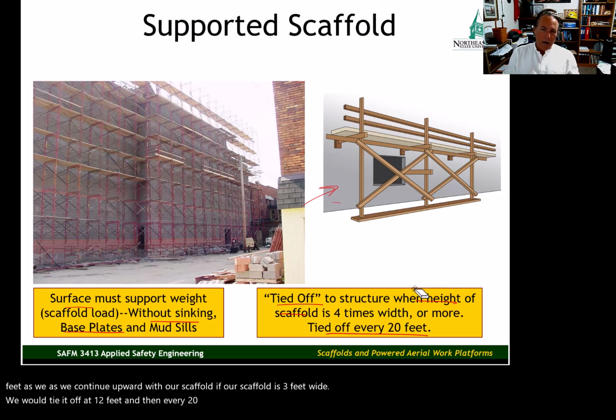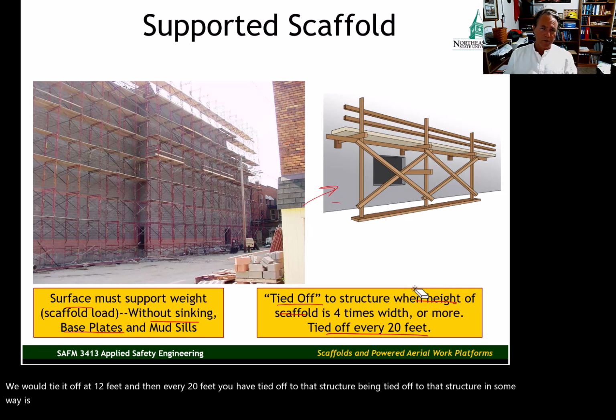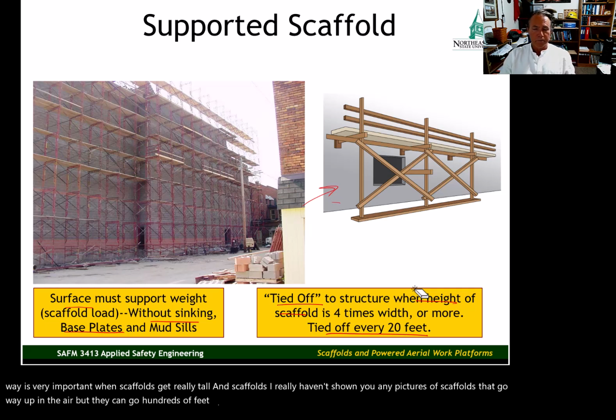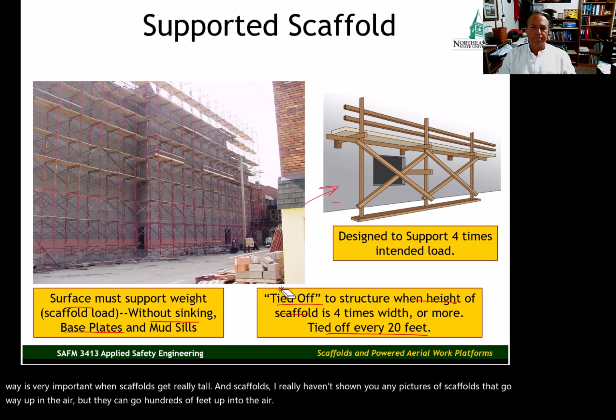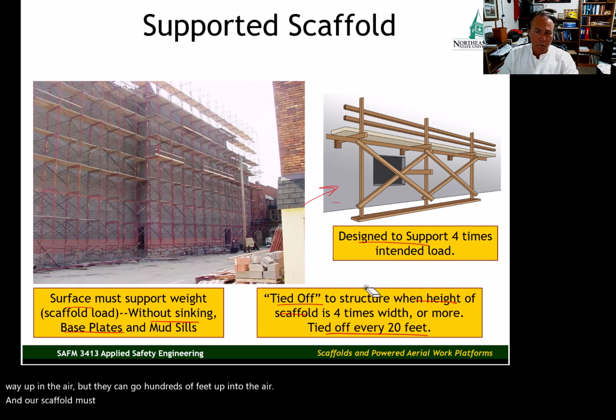Being tied off to that structure in some way is very important when scaffolds get really tall. And scaffolds, I really haven't shown you any pictures of scaffolds that go way up in the air, but they can go hundreds of feet up into the air. And our scaffold must be designed to support 4 times the intended load, as we mentioned previously.